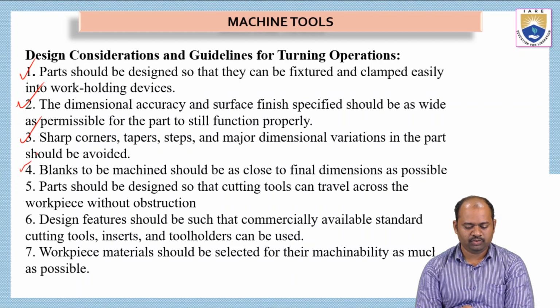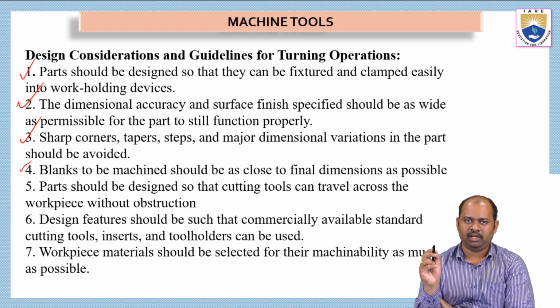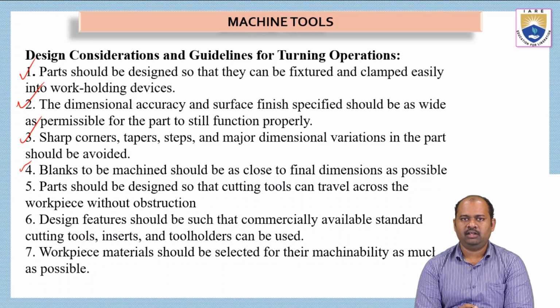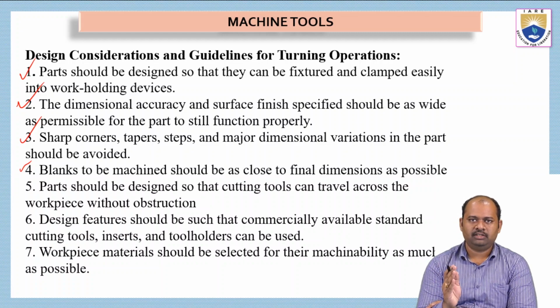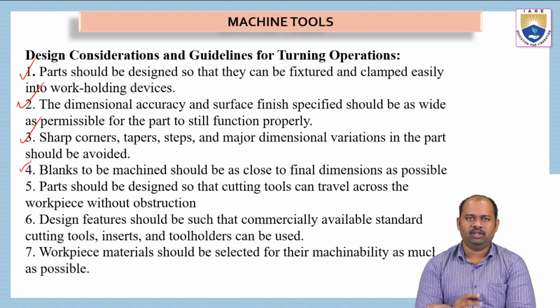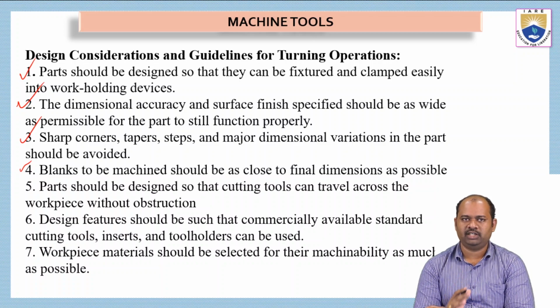And then parts should be designed so that cutting tools can travel across the workpiece without obstruction. So the design should be in a manner where the tool which is moving along the length of the workpiece should be easily movable. There should not be any obstructions.